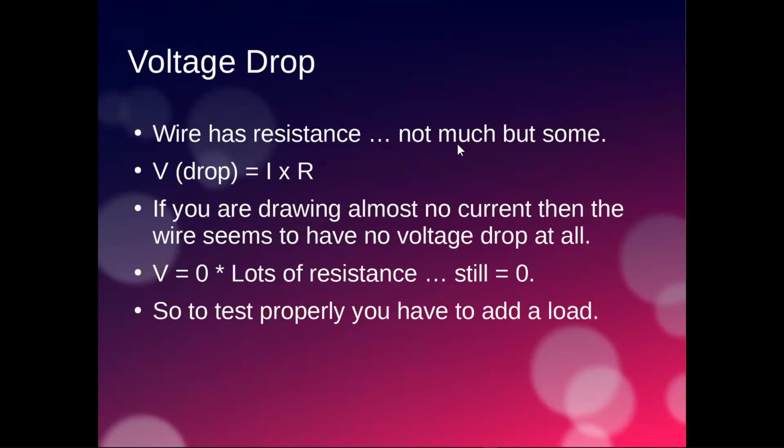But as you start to turn pixels on, and the more pixels you turn on, the more current that goes through it. And so the voltage drop will start to increase. So you have to be careful how you test voltage. If you ever want to go and test to see what the voltage is on your pixels, turn the pixels on and then check the voltage. Don't check the voltage without the pixels being on.